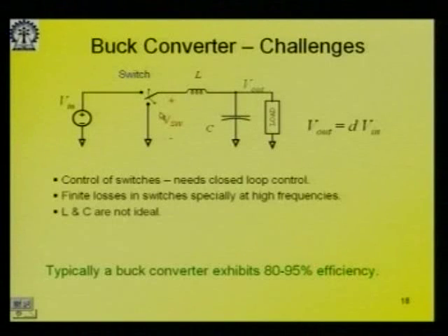You may say, okay, it is a simple buck converter, so maybe it is not so difficult, but these days there are lots of general cases where you will have one input voltage supplying 5 different loads at 5 different voltages, each one requiring different amounts of current, right. So, controlling the switches under those conditions will be a challenge. And then there is another kind of converter which I will come to, called a boost converter. It also brings its own problems.